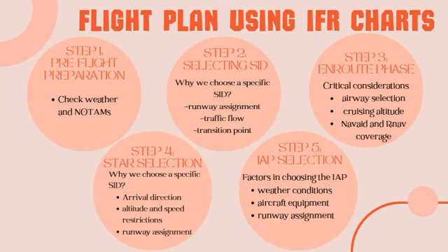Also, traffic flow. Air traffic control uses SIDs to manage traffic efficiently, minimizing conflicts. And the transition point. A good SID leads smoothly into the en route structure, reducing workload. For example, if the SID includes altitude restrictions, we ensure that these are manageable based on the aircraft performance and any airspace constraints. Step 3, we plan the en route phase.